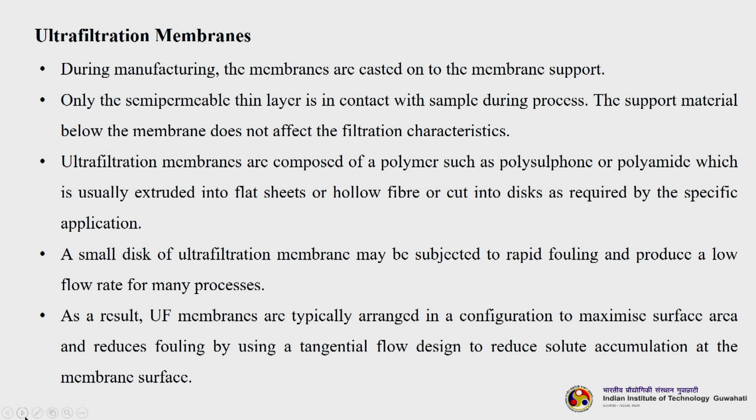So, when you are making ultrafiltration polymeric membranes, it is very easy to do that. You can make various shapes, hollow fibers, flat sheet membranes, spiral wound membranes, but when you talk about ceramic ultrafiltration membranes, you cannot have different types of shapes and sizes. Though plate and frame ceramic membranes are available, most of those are actually tubular, right. Plate and frame has a lot of problems, but as you know, ceramic membranes are usually brittle and very heavy.